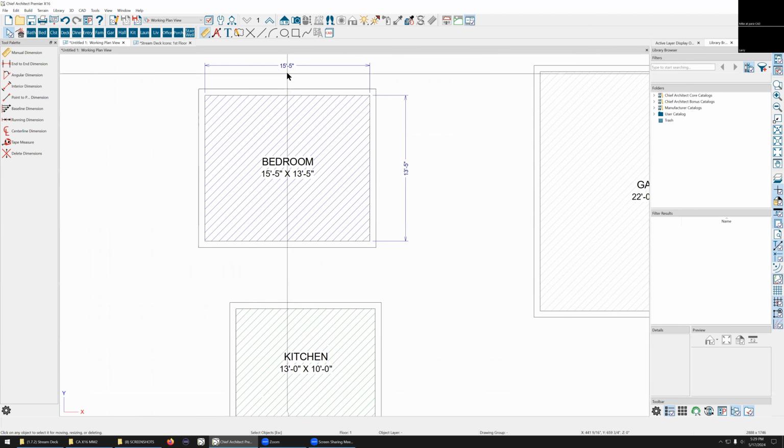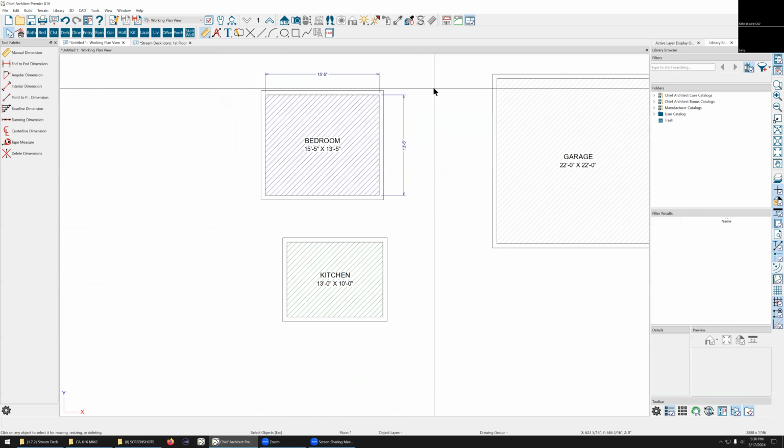You see what I'm doing right there is I'm in my mind doing the math of adding 7 inches to get a 16-footer. It should be 15.5, or 11.5, or 17.5, an odd number on the feet and then 5 inches on the inch. So that would make it solid. That'd be exactly like this one's a 16 foot this way or a 14 foot this way. And so you have no waste.